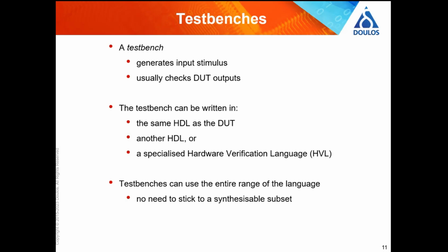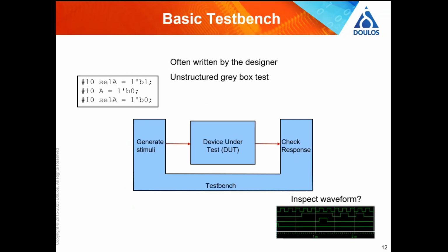And the nice thing about verification is you can use the whole of the language. So I don't know what your levels of expertise are, nor certainly not the people listening online, but you will be aware if you've done any design that you can't just synthesize anything. There's a subset of the language that is synthesizable. But whereas with your test bench and your test code, you can use the whole language. And if you're using SystemVerilog, well, you get to play with fancy object-oriented stuff, which if you're an engineer that likes playing with new things, that's going to be of interest to you.